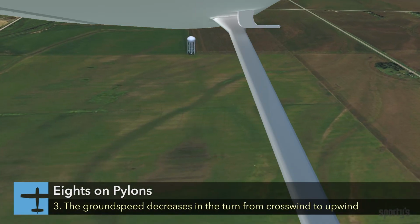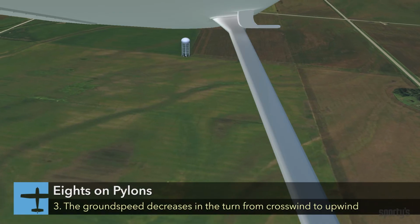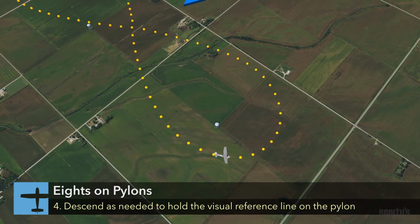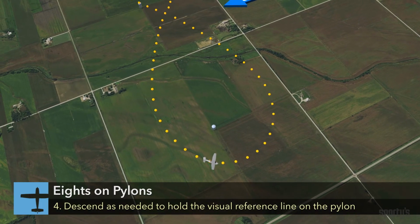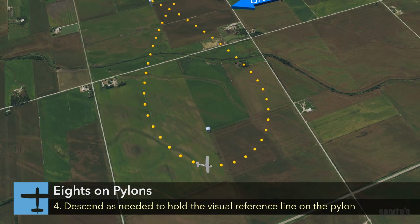As the turning airplane heads to the upwind side of the pylon, the ground speed decreases, which lowers the pivotal altitude. As a result, the pilot must release back pressure and descend to hold the visual reference line on the pylon. The pivotal altitude is critical and changes with variations in ground speed.